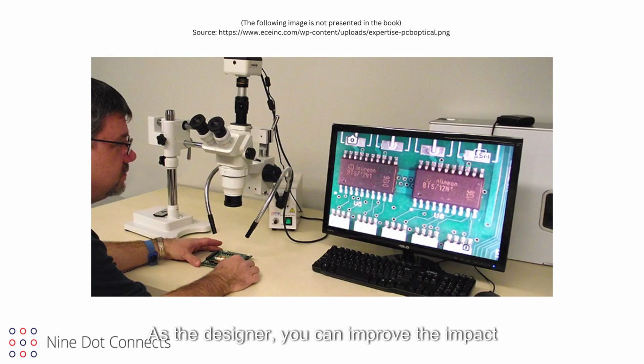As the designer, you can improve the impact of the cleaning by being strategic about device spacing, device alignments, device selections, and cautious silk screen usage. Here is a partial list of the considerations made by the assembler when choosing the optimal cleaning method for a given board. What are the contaminant sources?